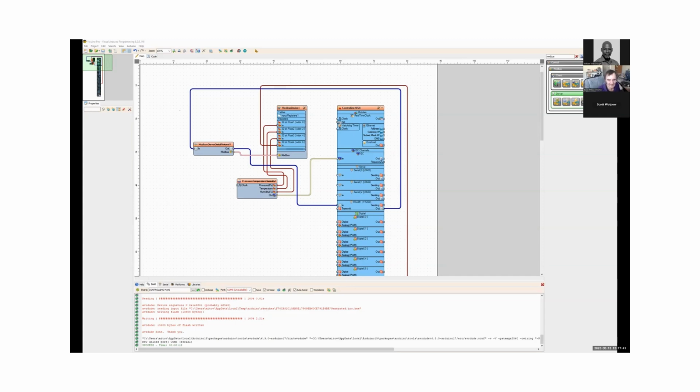I selected the right COM port. The Modbus is RTU, which is the serial COM port connection. Then I clicked to connect. Click here. We're looking at input registers, and our format is 32-bit floating point format. And here is the data.